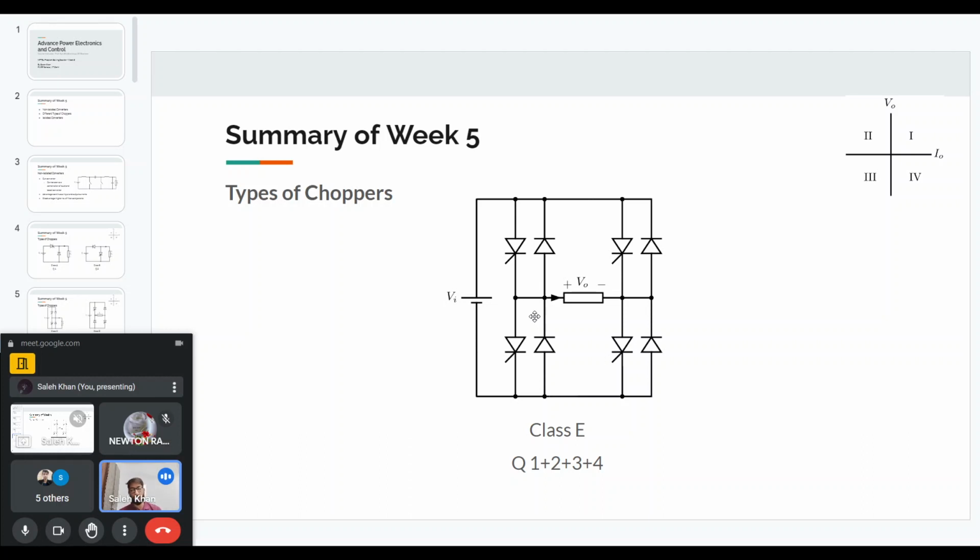For the motor, the motor can be running in one direction, and if we then apply brakes in that direction, the current will be reversed. So for the same polarity of voltage, the current can be reversed. That is forward braking.